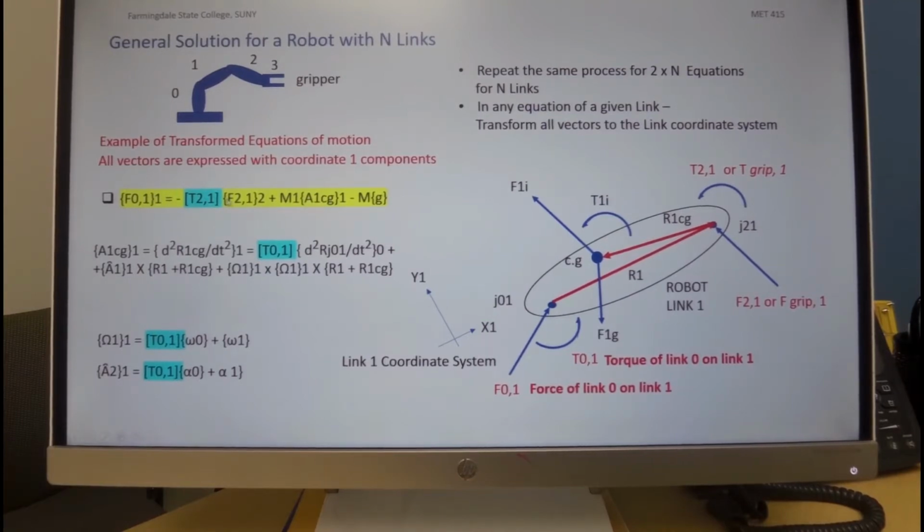So here's an example. Just took one example. The Newton's equilibrium equation with the solution, F21 was probably represented in coordinate system 2, this force over here, when it was solved. But now we have to use it in coordinate system 1, therefore we have to hit it with a transformation matrix from coordinate system 2 to 1, a vector which was represented in coordinate system 2, and this will bring it as a happy camper in this equation, and it could actually be added and subtracted to all the other components which will be represented in coordinate system 1.